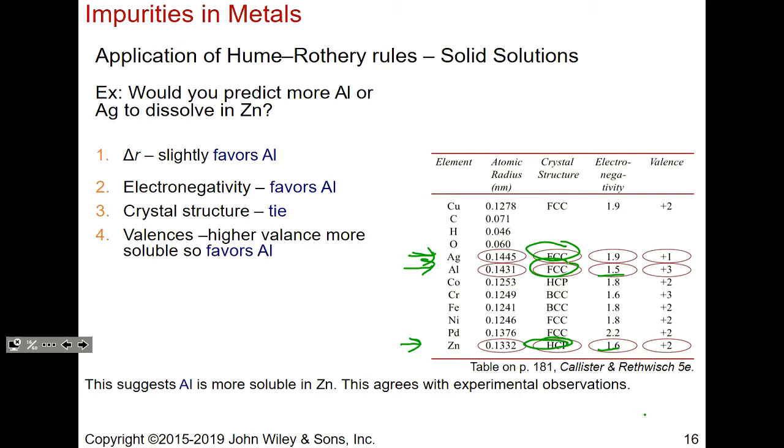If you're just looking at the 2D projection of FCC 111 and the HCP basal plane, the bottom or top plane of HCP, they look identical. So you would need to have more information on that. So there is a plane where this could exist. If you look back at your chapter 3 crystallographic systems, or crystal structure slide deck, you'll see this illustration, and it's also in your textbook if you'd like to refer to that.